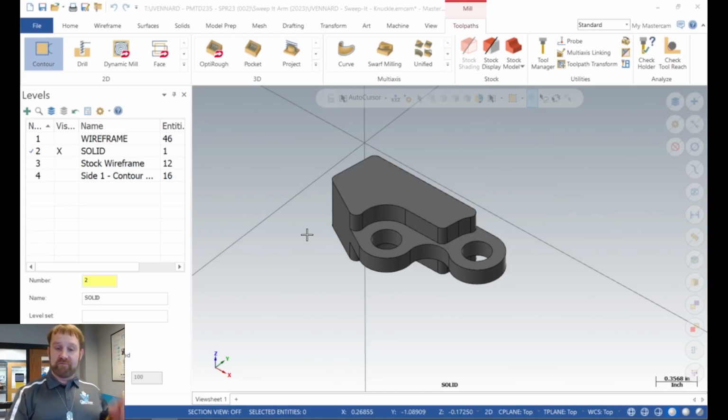So my first step is I set up my jaw geometry. We've got the top side of this part done. We've got to get it flipped over, faced off, deck off the back side, and then machine the little step and then chamfer everything on the back side. That's what we've got left to do. So I've got to be able to flip this part around, clamp on it, and machine the back side. Pretty cut and dry. But here's how I create the geometry to do that.